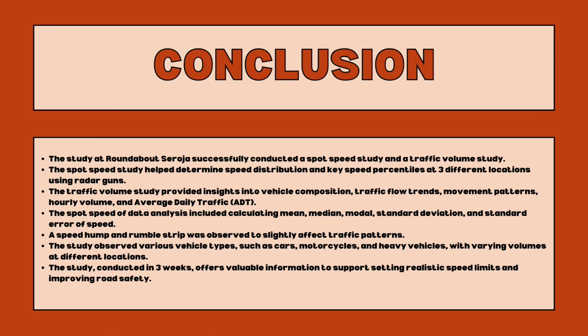The collected data allowed us to determine the statistical analysis that includes mean, median, mode speed, standard deviation, and standard error of the speed. Traffic volume study was conducted to enable us to understand and determine the vehicle composition in the traffic flow stream, to observe the traffic flow trend and movement pattern, and to estimate hourly volume and average daily traffic, ADT. The traffic volume study provides valuable insight into the vehicle composition, traffic flow trend, and movement